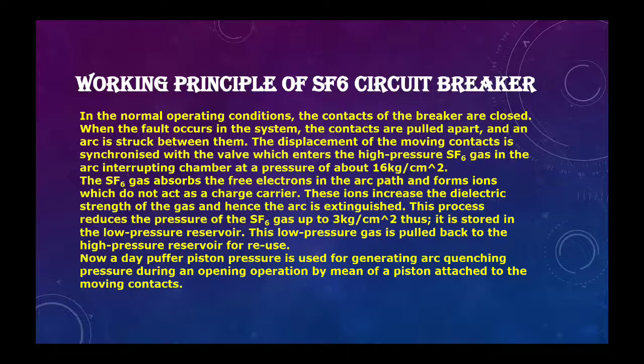Nowadays a buffered piston is used for generating arc quenching pressure during an opening operation by means of a piston attached to the moving contact. So that is the basic working principle of the SF6 circuit breaker.